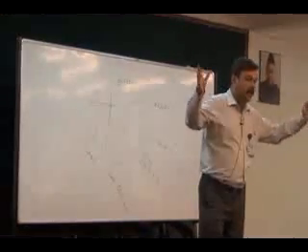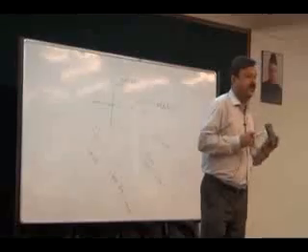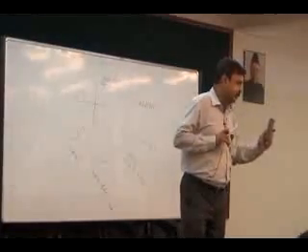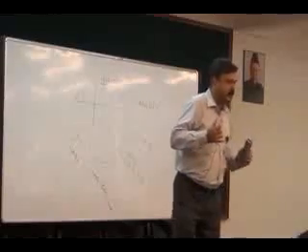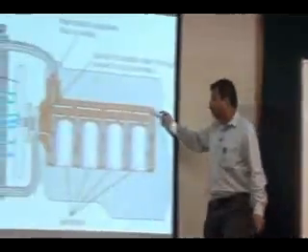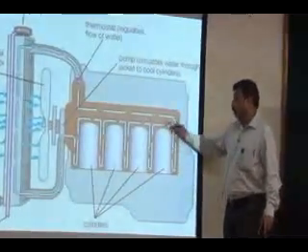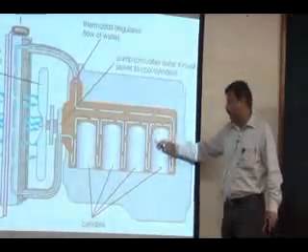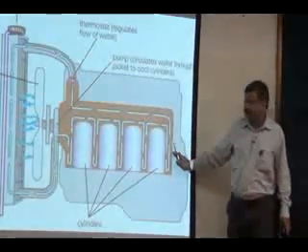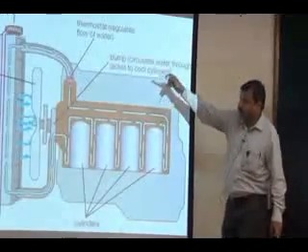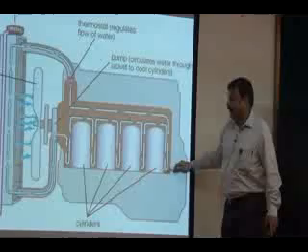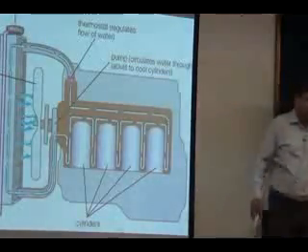The cylinder block is manufactured only by metal casting, because very intricate shapes can be manufactured by metal casting only. So the hole for the cylinder, the hole for the cylinder liner, and the water jackets can be manufactured only by casting. The water comes into the water jacket and then goes out as hot water.